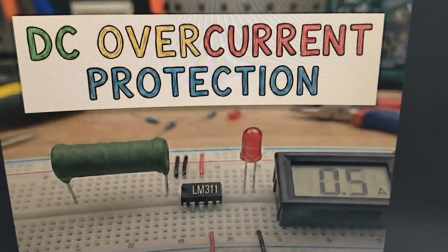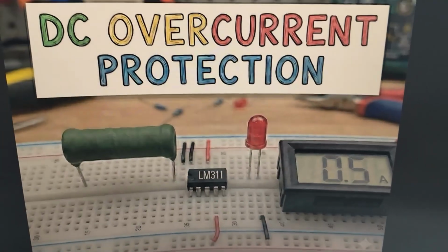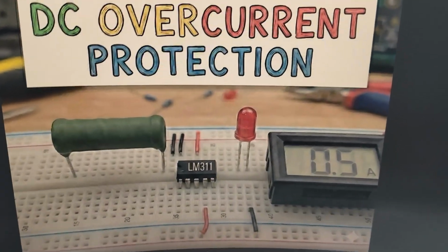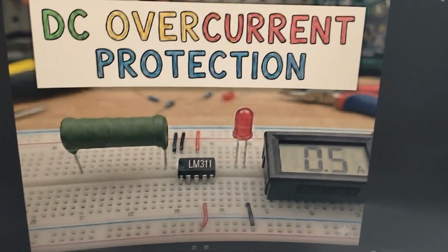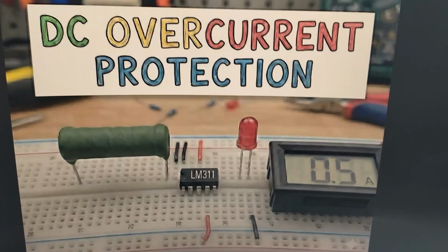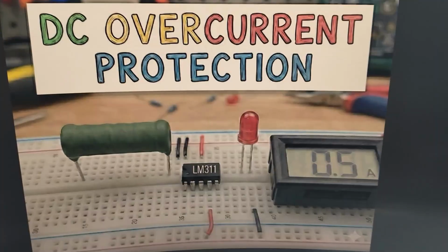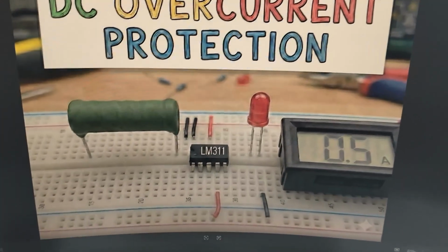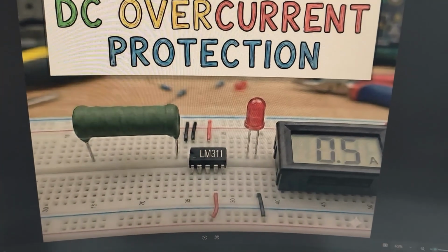As we know, AC overcurrent protection is basically the MCBs in your house, and of course overcurrent protection handles short circuits too. Those MCBs are rated for a certain amount of current, say 10 amps, or if it's for higher power maybe 30 amps. But that is for AC, and AC has a zero crossing, and those operate on a different architecture.